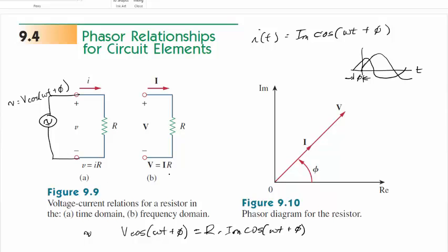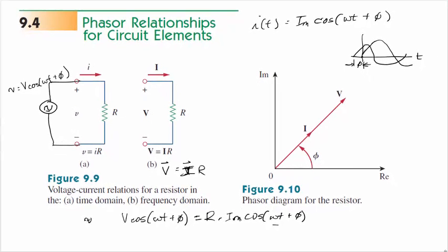So in our phasor notation now, phasors are like vectors, we have that same linear relationship conveyed in our phasor notation. So this is the function of time notation, and this is the phasor notation, which is a function of frequency. Remember the omega t is always implied in here, although not explicitly written. We will see coming up how that makes it easier for us. Now if we move on, I see my little markers are off a little. Let me move this. There we go.